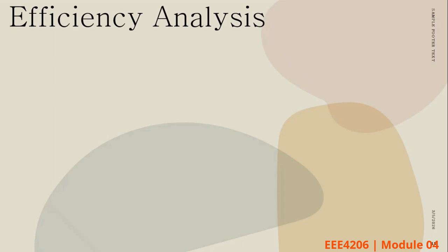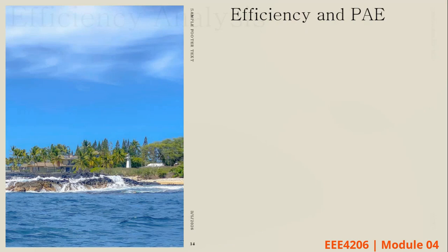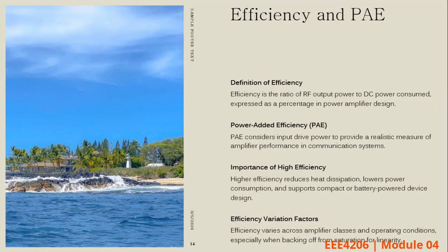And while discussing transistors, you need to understand the biasing effect, because for each class of the transistor, there is a way it is being biased. For example, in class A, it is biased in the middle of its operating region. For class B, it is biased at the cutoff point. Okay, so you need to understand some of these biasing techniques, and you've done transistors. So when I talk about biasing a transistor, you understand.